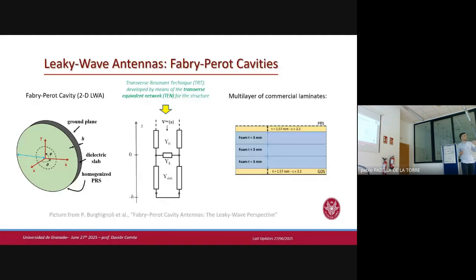The periodic structure can be homogenizable or not, uniform or periodic. If this periodicity, this slot, is small with respect to the wavelength we are working on, you don't see this periodicity. But still, that doesn't mean that the field does not interact with the modulation. That's the point. So it's a partially reflective surface, or sometimes screen. In this case, the periodicity is not so important anymore. Still, you can apply the Leontovich boundary condition that probably you know.